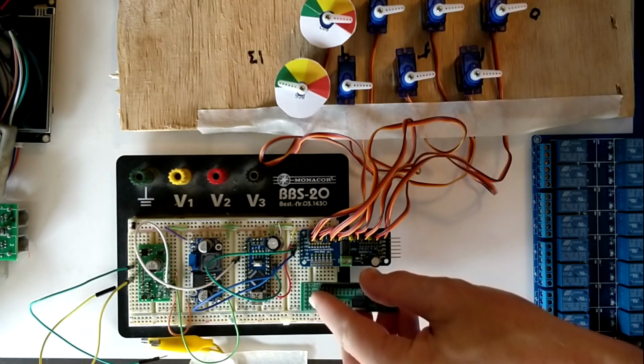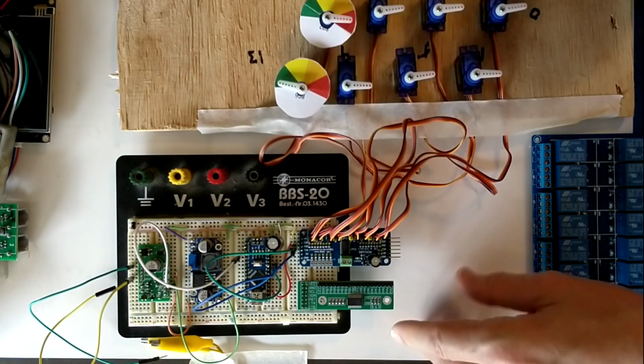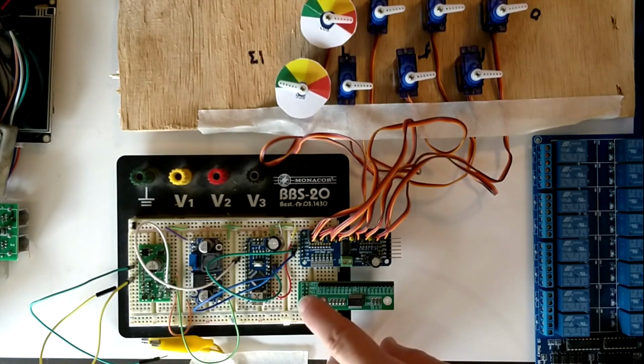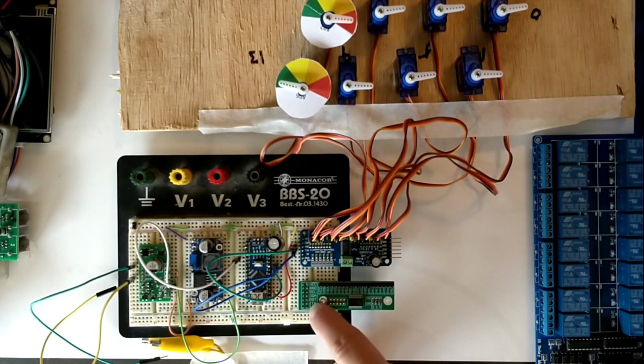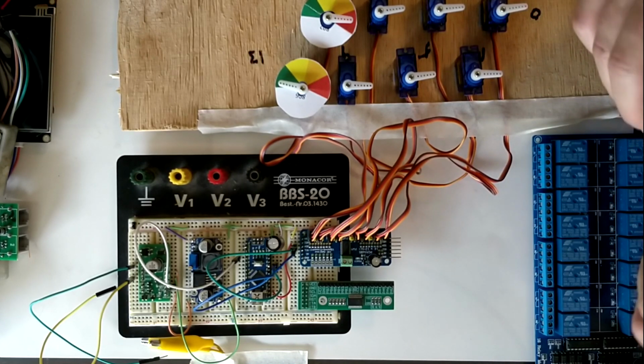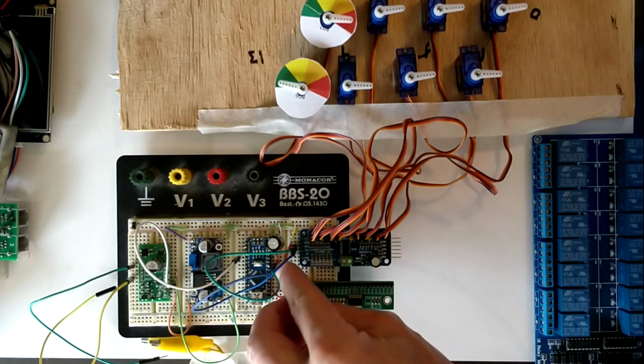So I'm placing it right next to the PWM driver, and what it needs is VCC and ground, and SCL and SDA for the I2C bus, and then the other three connections are the reset pin and two interrupts we are not going to use. So what we need to do is putting on VCC and ground. Now VCC, this time I'm going to take from the 5-volt pin of the Arduino, which is right here.